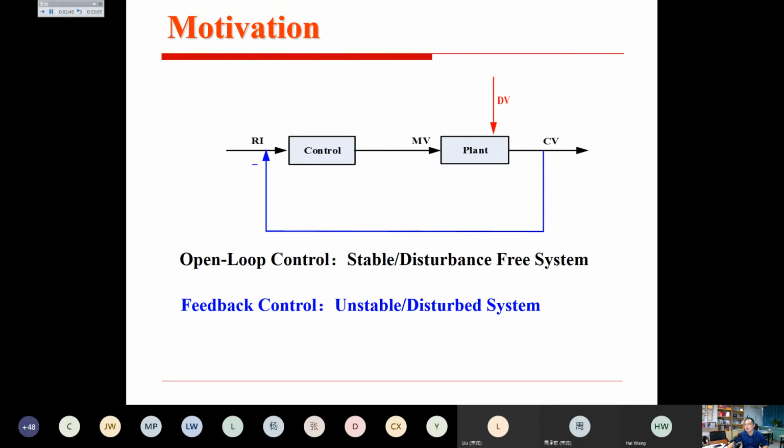But there's a problem. If you look back at some principle books for automatic control, we know the feedback control is not a good control for rejecting disturbance, because between the tracking error and the disturbance, you have a controlled plant here. If the plant dynamic is slow, then in the presence of large disturbance, it will take a long time for the error to become large.